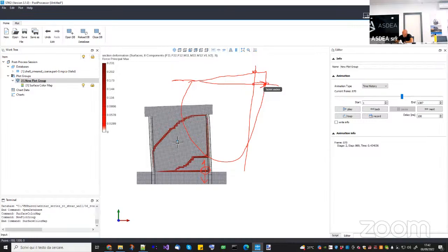Then my surface will shrink according to an exponential softening, and let's say I go up to this point. With this exponential softening, even if I'm hitting the surface orthogonal to this crack, what I'm doing is that I'm shrinking the entire surface. So this is my new surface, basically.